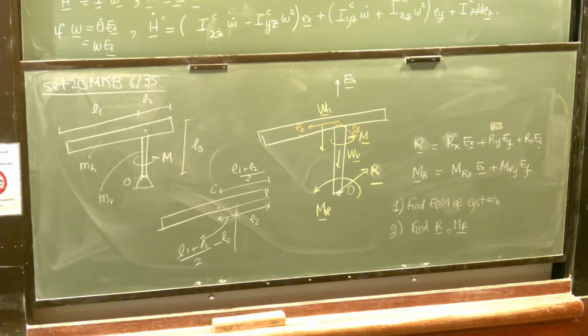Good. What about the angular momentum part? Oh, yeah, I haven't done that part yet. Okay, come on. Okay, did I check your work? Wait, I'm confused about how to find the products of inertia after. Okay. The products of inertia about the center of mass are 0. Maybe use the parallel axis theorem. Okay. About the center of mass are 0, but you have to calculate this AX, AY, or AY, AZ term.